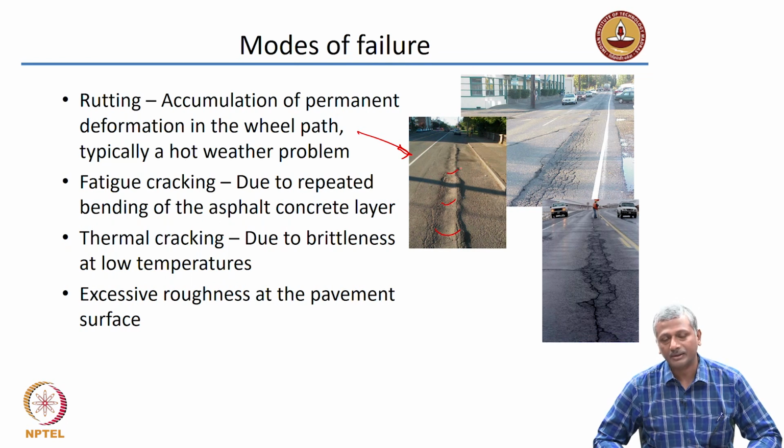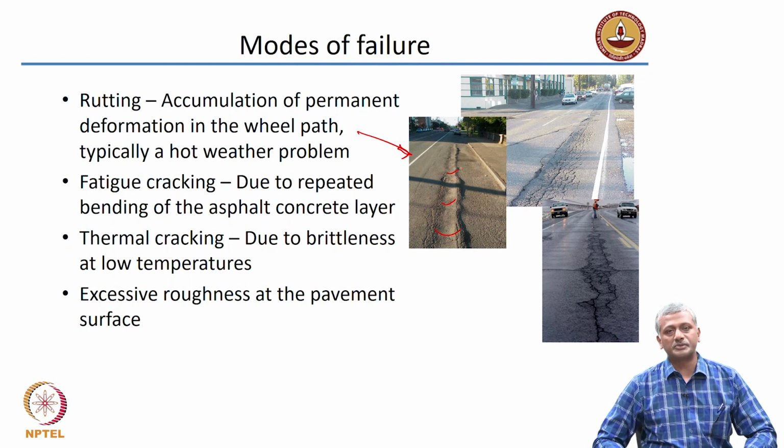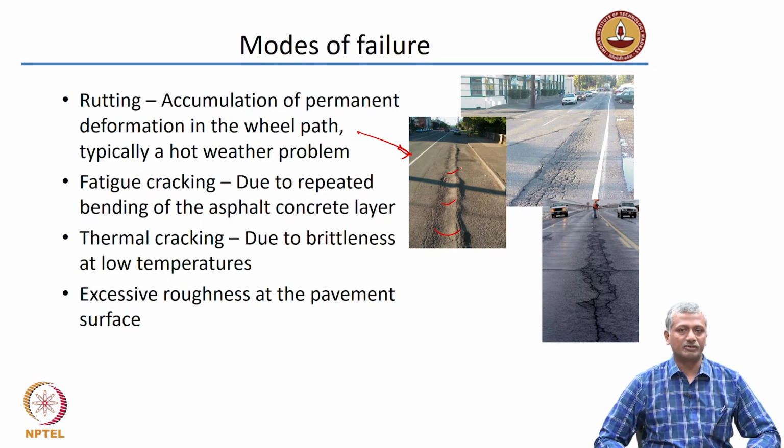That's called rutting. And rutting is a very common phenomenon, especially in summer months when you have significantly high temperatures, and that may cause the asphalt to start flowing.